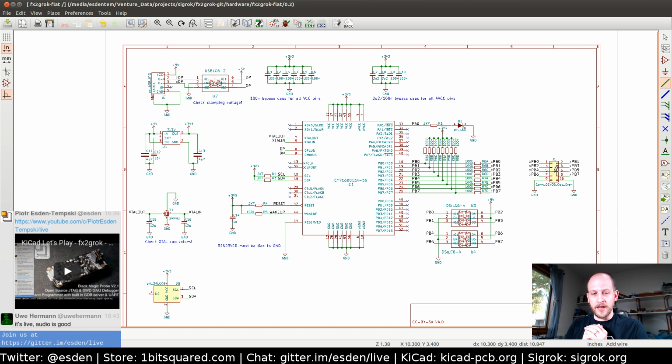I don't like through-hole components because that requires either manual soldering or an additional machine, like a selective soldering machine. If you are interested in what that is, Adafruit has one of them. It's a pretty awesome tool to have in the shop, but our operation here is not big enough to afford tools like this. Anyway, that's why there's no through-hole components on here.